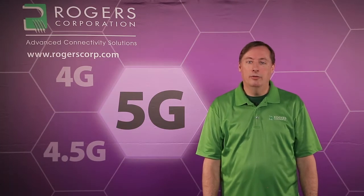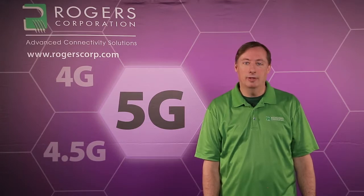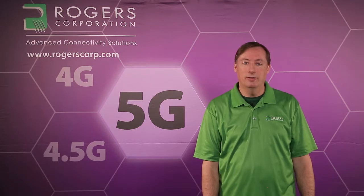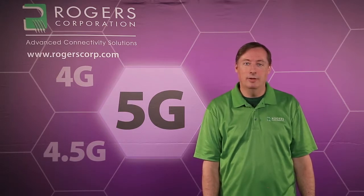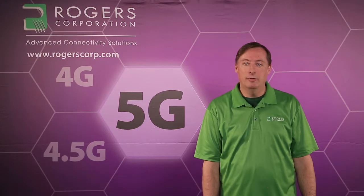Now there are other issues associated with copper surface roughness, and one of them is how the copper surface roughness impacts the phase response of the circuit. Essentially, a rougher copper surface will slow the phase velocity of the circuit, and the circuit will perceive that as a higher dielectric constant. Even if the material stays the same for dielectric constant, a slower wave is perceived as a higher dielectric constant by the circuit. That circuit perceived dielectric constant is what we call design Dk, and it is sensitive to copper surface roughness. At millimeter wave frequencies, this can be a very important factor to understand.